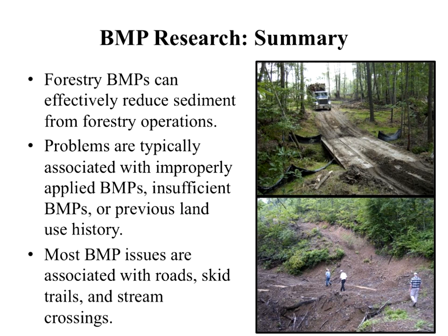All right, I'll basically run over time here. I think I basically said what I wanted to, but we know that forestry BMPs can reduce sediment. We know that they can. Where we have problems are where the BMPs aren't properly applied. Maybe we're not using enough BMPs, or we have some issue like the old gullies, previous land use history. The major things that most states need to focus on are, again, the roads, the skid trails, and the stream crossings. There's always other problems, but those tend to be the big ones.